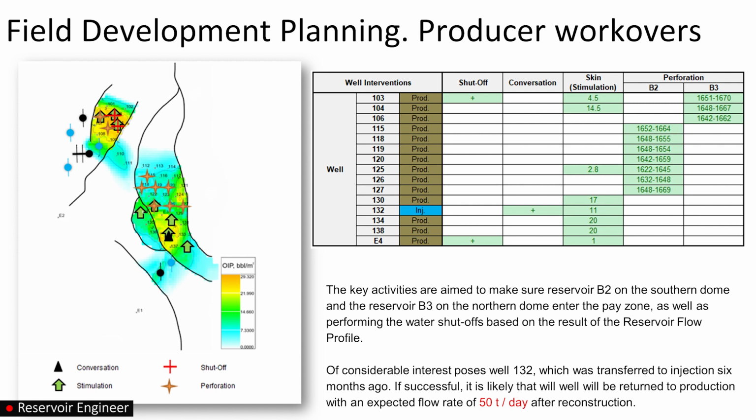Also, according to the results from the well testing specialist, there are wells with significant skin factor. I also suggest that we conduct stimulation on these wells by processing the bottom hole zone. The final priority settings will be made by the economist.